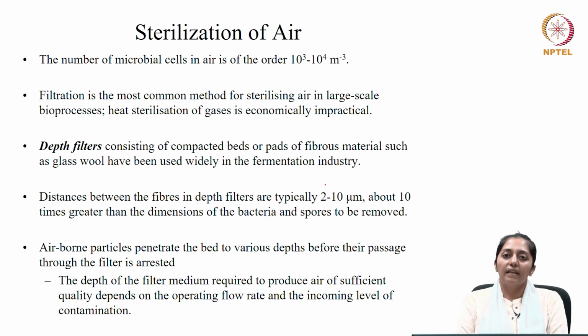So, for sterilizing air, generally depth filters are used, which consist of compacted beds or pads of fibrous material such as glass wool, which have been used widely in the fermentation industry.